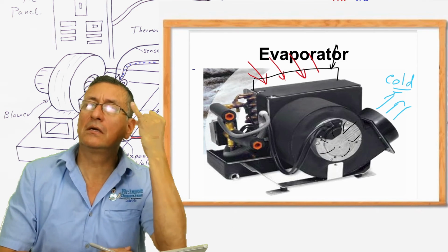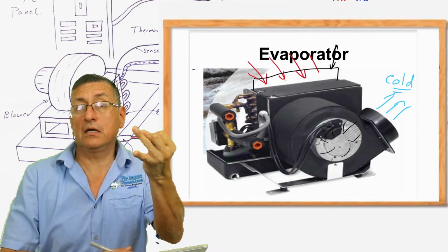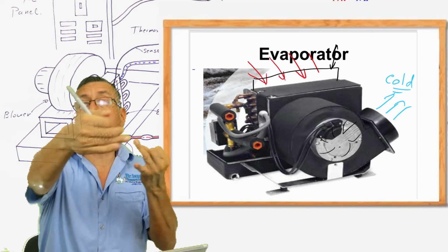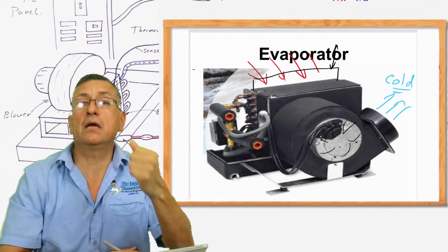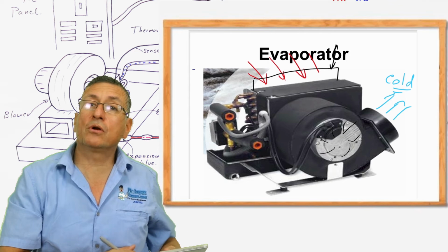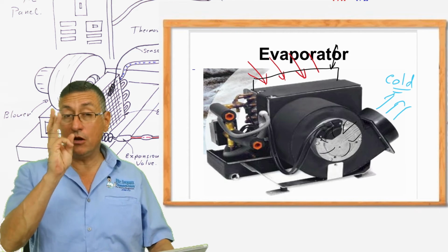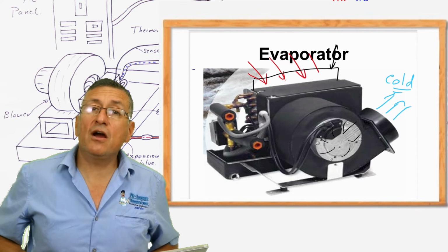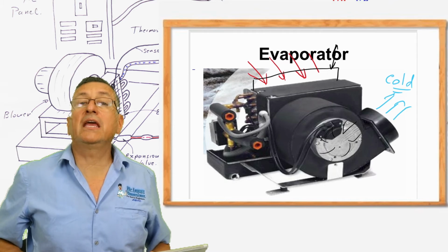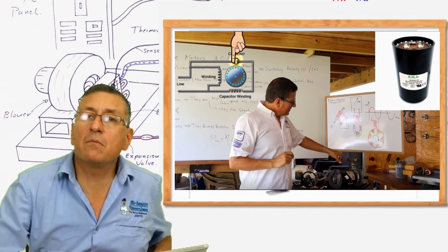One reason is because the air filter is clogged. Other one, no filter, and air with dirt, with debris, clogs the radiator. And number 3, because the blower motor is damaged. Be careful with this. The number 3 is very important. The majority of the evaporators have a capacitor on the electric motor of the blower.